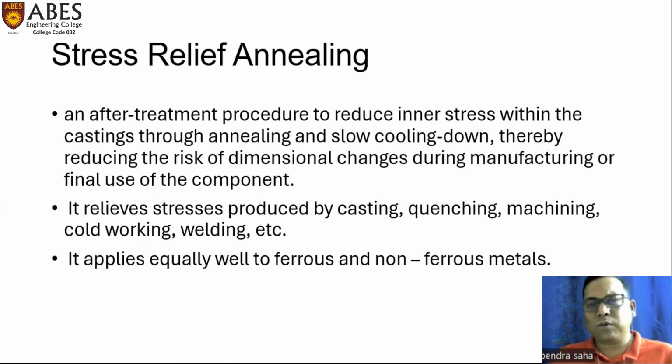So stress has to be removed from the material. For stress relief annealing, the metal is heated just below the recrystallization temperature without changing its phase anyhow. And after a very short time, the stress is removed from the material. After stress relief, when the stress has been reduced in the metal, the metal which comes out from grinding or machining can easily be used for production.